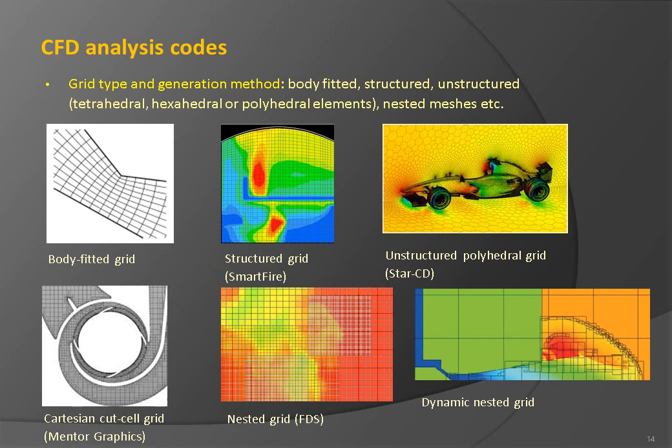They are often referred to as overset or nested grid approach. They allow the use of different grid types in the same simulation domain. These grids are not embedded but overlaid, with the flow field being interpolated between different grid levels. Although not widely applied in the CFD community, such techniques offer the maximum degree of flexibility.